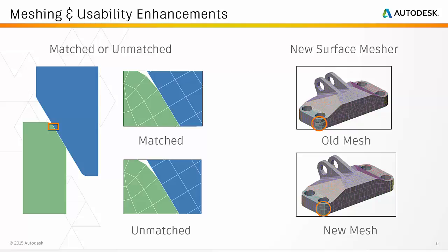In addition, a new surface meshing option called Delaunay plus Advancing Front Technique has been added to the 3D mesh settings dialogs. The legacy surface mesher used the Advancing Front method only. Now, you can use the combined Delaunay and Advancing Front meshers to produce more uniform rectangular surface elements. This mesher has the highest success rate when you do not perform surface splitting during CAD model importing and when the Create Matched Mesh Between Parts is not checked.